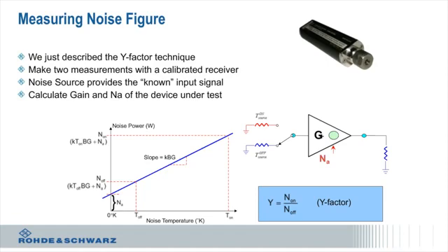So what are we doing here? Well, what we really want to know is if I have 2 points on a gain curve for an amplifier, obviously an ideal gain of an amplifier would be a straight line with a slope determined by its gain. But if I pick 2 points off of this curve, I can determine what the noise figure added from my device is.